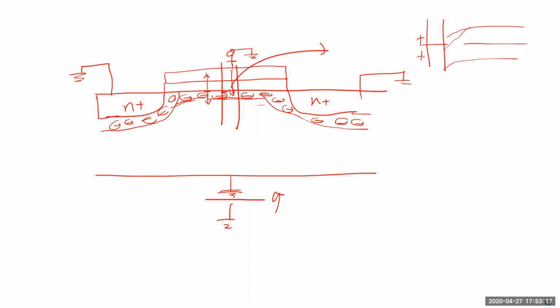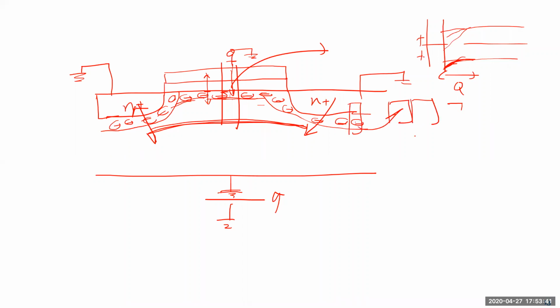But in this case, because the depletion is coming from the side, it actually goes up. But I think most people will ask, why is it going up if you already have a depletion here? Yes, that's the problem, because this potential difference should give you this depletion width, but that's because of this PN junction here. So if I take this PN junction and draw the band diagram, then yes, this band is completely bent like this, but that's different from this one.